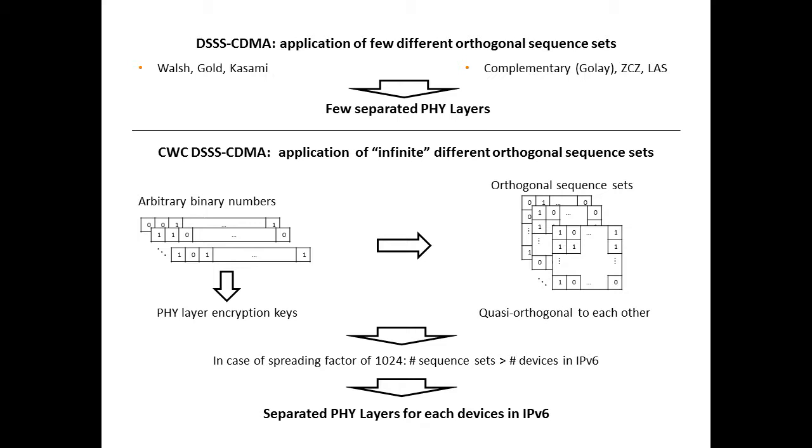Such a technique cannot be realized by other usual encryption schemes at higher layers of the OSI model, so this is real physical layer encryption, and it is classified as a polyalphabetic cipher. Additional mixing of serial numbers of sequences in the set can be used to increase crypto protection. In conclusion, general features. First, identification. The receiver can identify the transmitter if it knows some pool of keys, and you can transfer data to a specific device. Second, information protection. You cannot even receive the signal if you do not know the key.